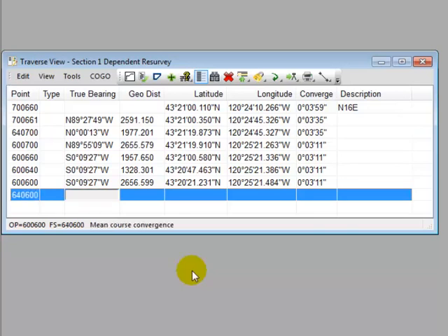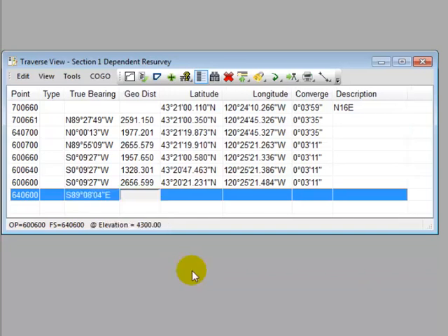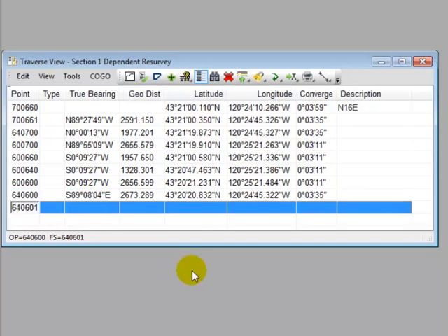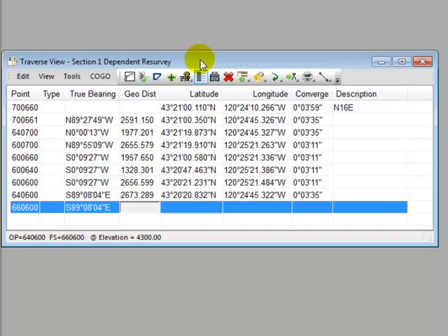The bearing is southeast now, so that'll be a 2, 0804. Distance is 2673. I know it's pretty boring to watch someone just enter data like this. Okay, let's come over next then and do our E16th on the south line, so that'd be a 660, 600. Again, we can extend that southeasterly line, distance of